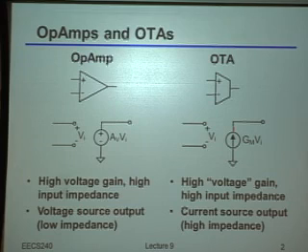You're actually moving from voltage into a current. But obviously in any real circuit, there's always an output impedance here, so you can indeed define a so-called voltage gain. Okay? Now, the reason I want to make this distinction, as you'll see in 1 second, is that depending upon whether you're using an OTA or an op amp, that's also actually going to change the way you're going to want to use these in larger closed-loop systems.